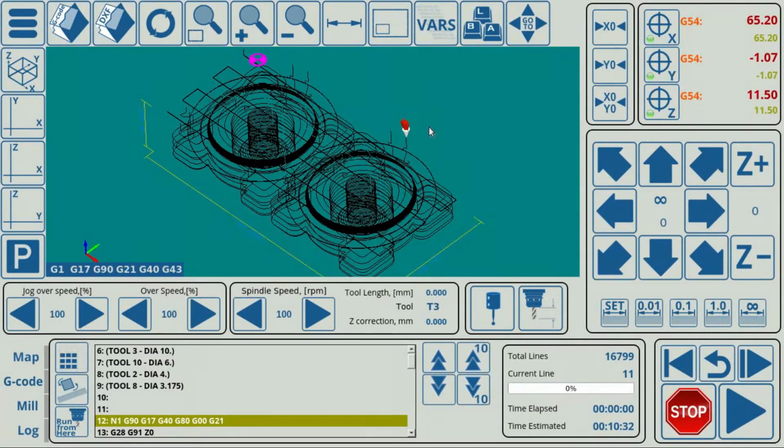And the reason we move the tool is typically because we can't actually reach it from the point on the machine that it is located at the stopping point, and we'd simply like to move it closer to the machine's edge. So this is a pretty common scenario on many machines, be it a milling machine or a plasma cutting machine with a plasma cutting torch. And there are solutions for this which allow you to then return back to the working point and to continue working despite this momentary interruption.